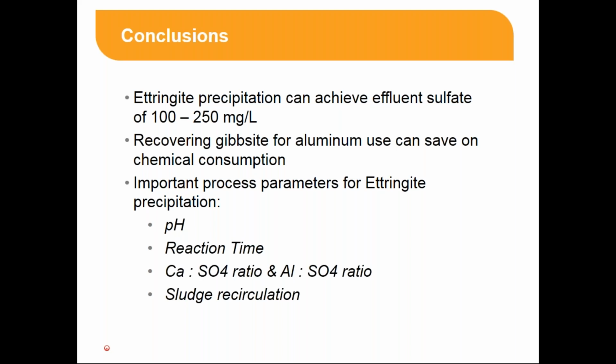Another important, critical parameter is reaction time. Based on our pilot study, I would suggest anywhere from 30 to 60 minutes of reaction time. Please note, temperature is also an important parameter. If you have very low water temperature, then you need to increase your reaction time.